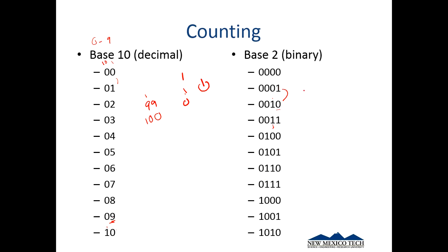So we go all the way through, and maybe we only have 4 transistors. That's why we have these 4 switches. What happens if I add 1 to that? Well, this one becomes a 0. This one becomes a 0. This one becomes a 0. This one becomes a 0. And if I don't have another transistor out here, that's it. We've accidentally reset our counter. So I'll talk more about that later on. But I just want you to see that.